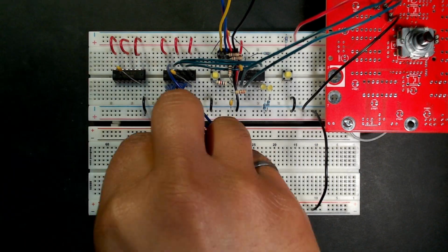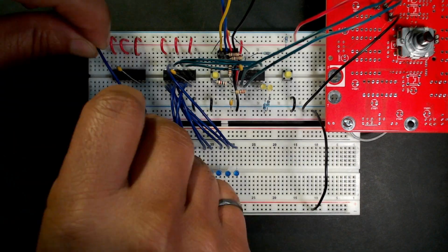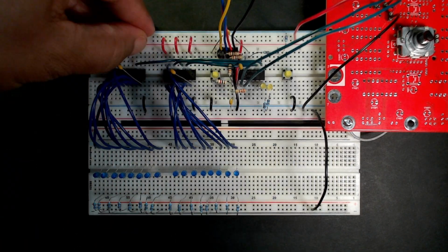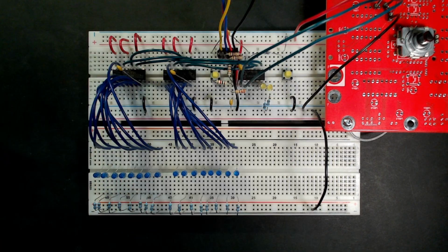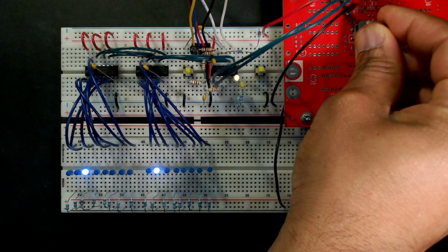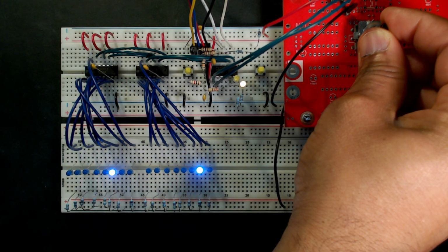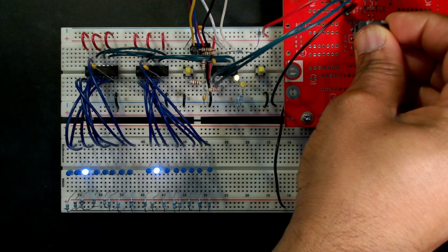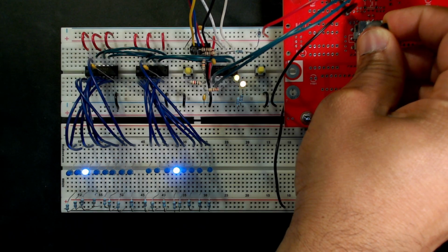And we can wire it up in exactly how it's written into our schematic, connect our additional 8 LEDs, and try to keep the wiring as neat as possible. That doesn't look quite right. It almost looks like a delayed copy of the first shift register. That's because we're still sending an 8-bit output. In order to fill the 16-bit shift register, we need to send a 16-bit output.